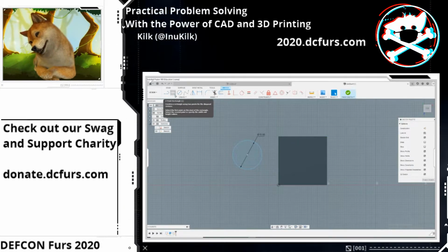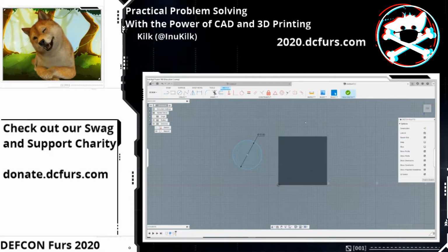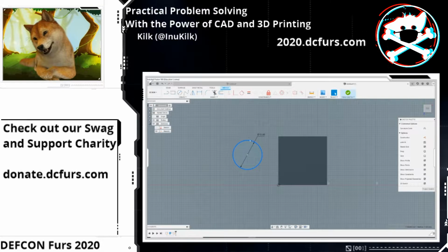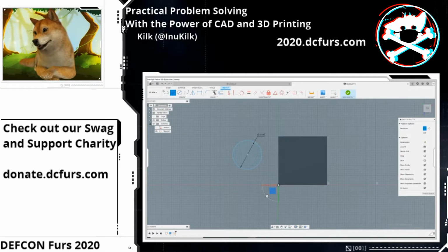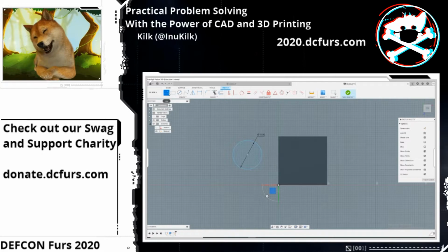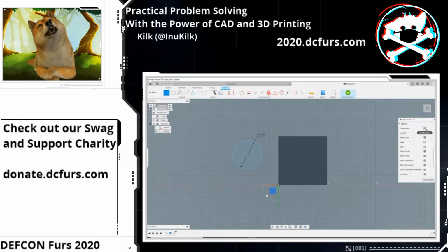We're going to create construction lines and add constraints to them to make it easier for you to dimension based off of the circumference of the circle instead of using the center point. We can do this by hitting 2-point rectangle. Actually, no, we're going to use the line tool. And you see where it says construction? Hit that and drag out. You can drag it out there.